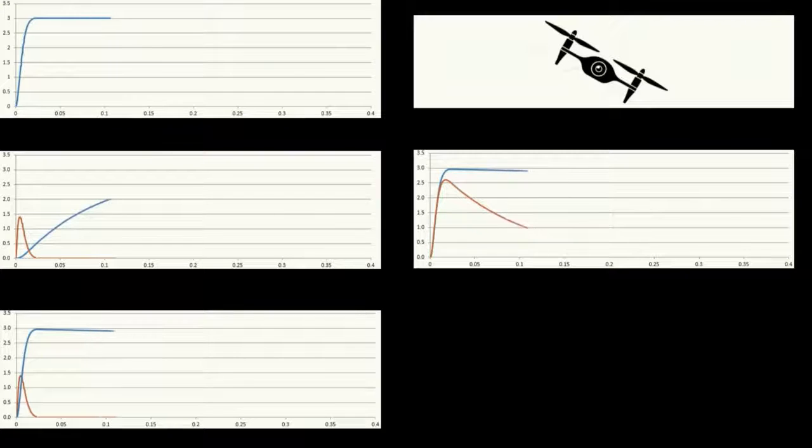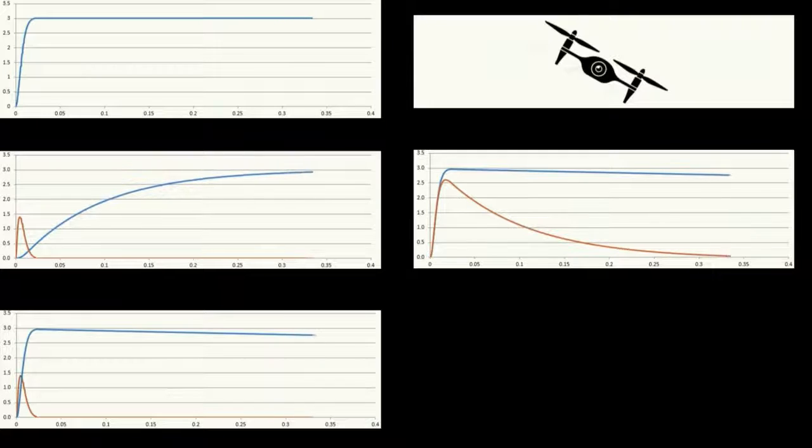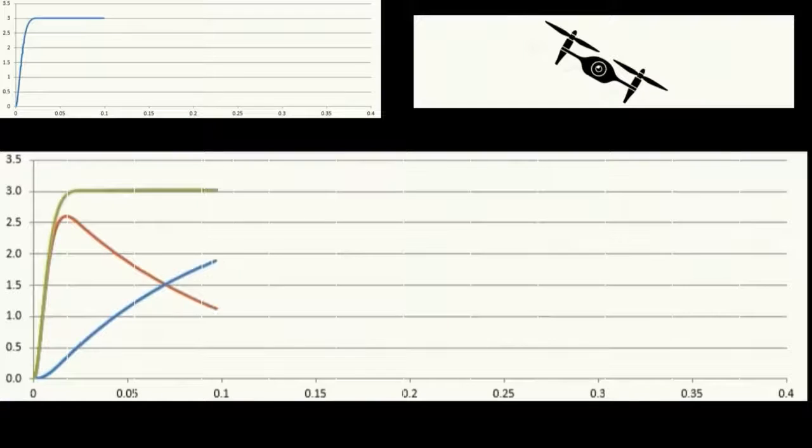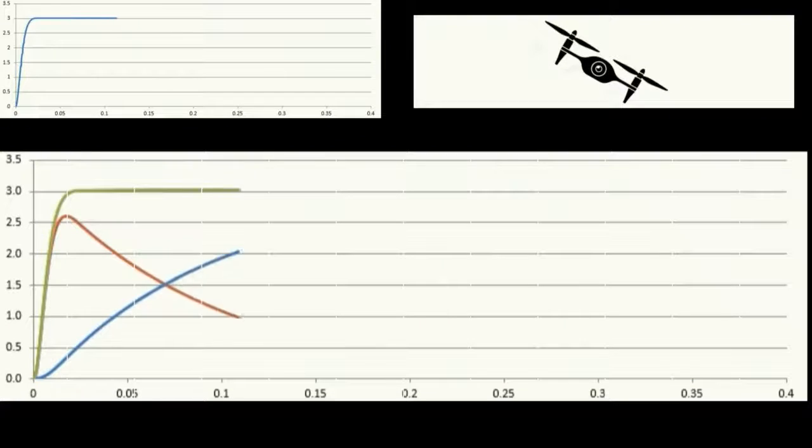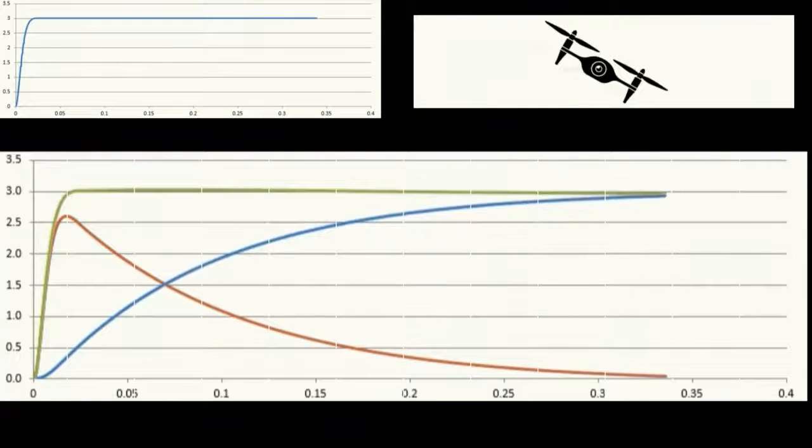Next, the circuit integrates this gyroscope signal. So again, the gyroscope signal is shown in red and the integrated signal shown in blue. This has a drift on it, which can be seen. If this integrated signal is then passed through a high-pass filter, this signal now appears. It's important to notice that the high-pass filtered version of the signal is kind of a mirror image of the slow-responding inclinometer signal, which can now be seen. By adding these two signals together, we get a very fast-responding output, which better matches the original response.